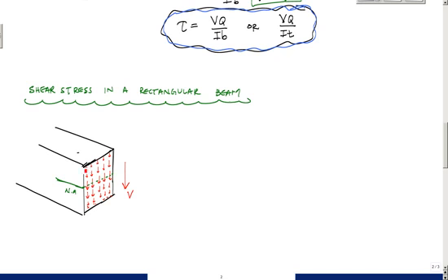And in fact, the profile here looks like, let me draw it in red again, the profile here looks parabolic with max over here. I don't know if you can see this or if this drawing has gotten too sloppy, but this is what the intensity looks like. These are my max shear stress, and this is a parabolic stress. So the shear stress profile is parabolic.